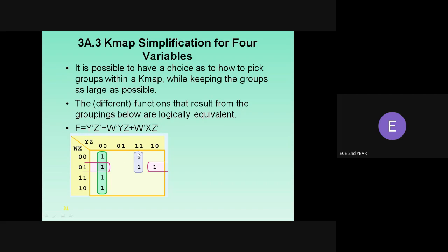And for the next possible grouping, this is nothing but 1 1. Here two rows we have to check, first row and then second row. If you check the first row and second row, it is 0 0, which is the same, and the second variable is changing from 0 to 1, so we cannot write the second variable.